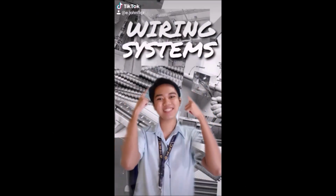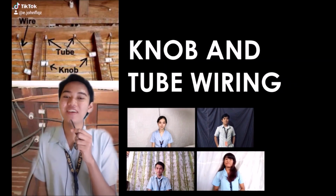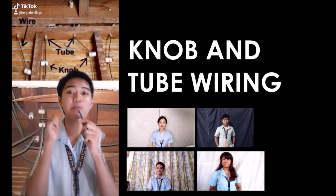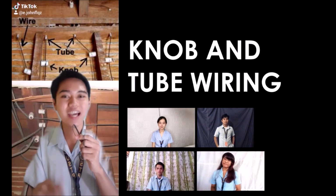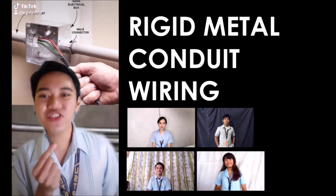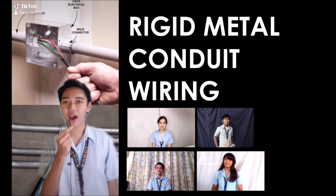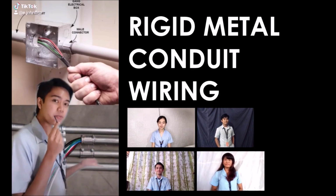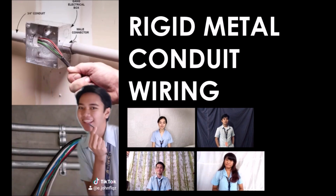In this chapter, we're going to discuss the wiring systems. Number 1. Knob and tube wiring consists of single insulated conductors supported through a porcelain knob and tube, and when wires run through walls, they are inserted through a loom. Number 2. Rigid metal conduit wiring. It is the best and most expensive type of wiring. It is fireproof, moisture-proof, mechanically strong, and it resists the normal action of cement.